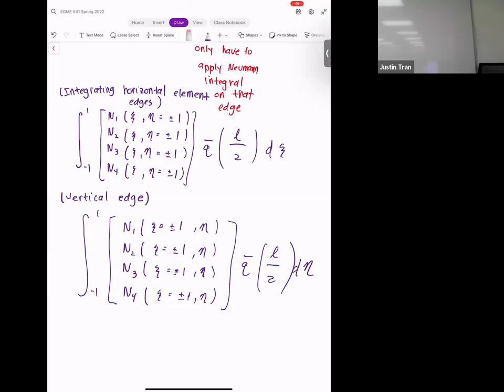So the shape function is used to basically interpolate, right? If you think back to our direct stiffness method, when we solve, we solve for the displacement. For general finite elements, you're doing the same thing. You're solving for the nodal solutions, but to form things like the element stiffness matrix and the element forcing vectors, you need to know how the solution varies within the element. As you go from node to node, how does the solution vary? That's what the shape function is used for. The shape function models how the solution varies between nodes, and that's needed mathematically for element stiffness.